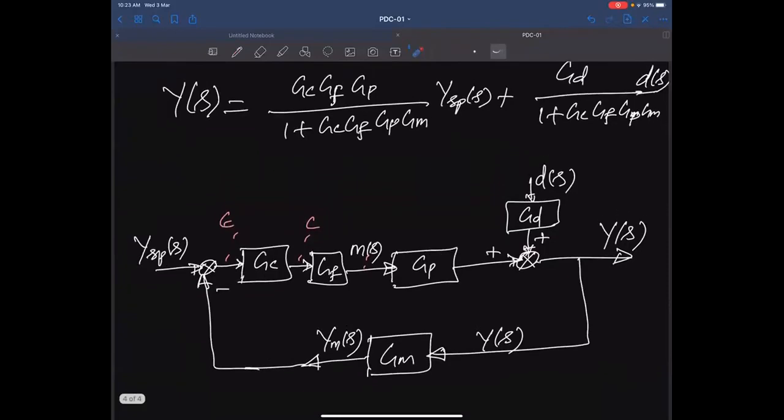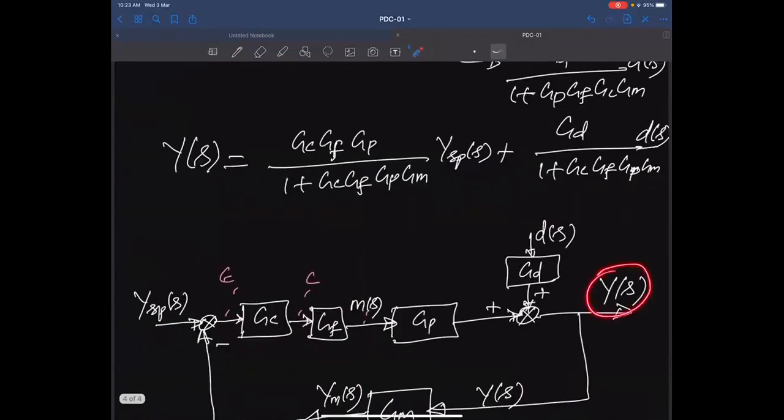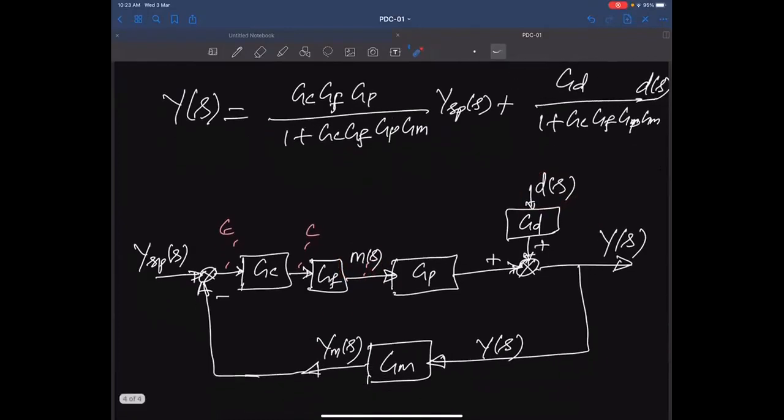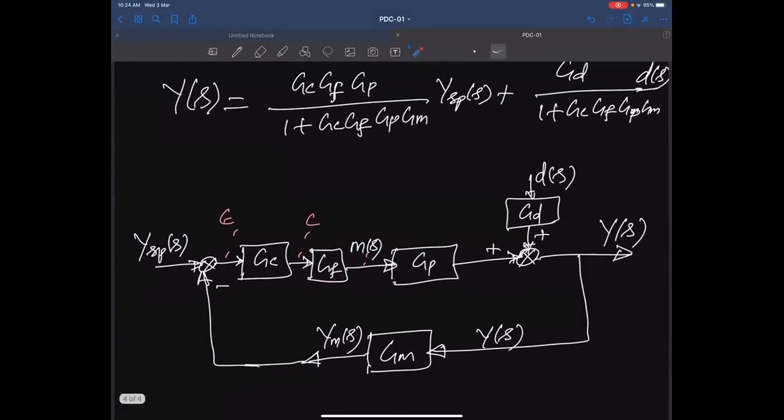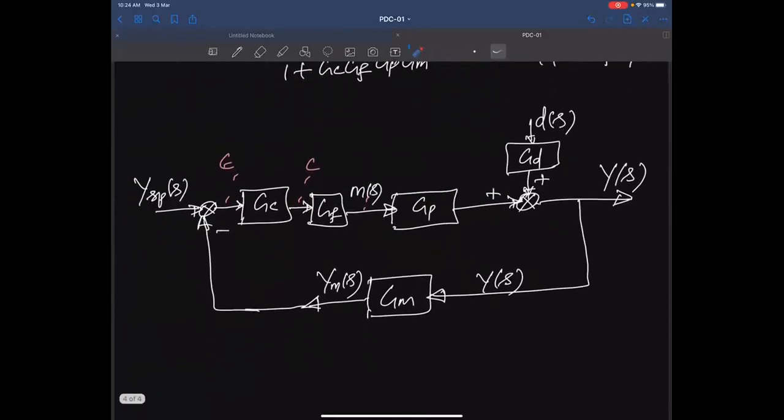I'll explain this again. So we are relating these output variables in terms of manipulated variable and disturbance variable. And manipulated variable is the thing coming from the final control element. So we take a measurement, and the measurement is compared with the set point, and the error amount is given to the controller, and controller is working on the final control element, and we have the manipulated variable. So this entire block diagram is now simply represented in terms of this algebraic equation. So this algebraic equation represents the connection of these entire elements in the loop. And here, what is a loop here?